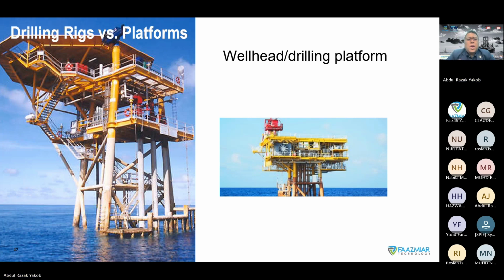This is what we call a wellhead or drilling platform. What determines this is, if you see at the bottom over here, this is what we call a drive pipe or conductor, where we will drill inside it. Yeah. So sometimes when I design the platform, I will also design it such that I can make use of these legs over here as part of the conductor as well.